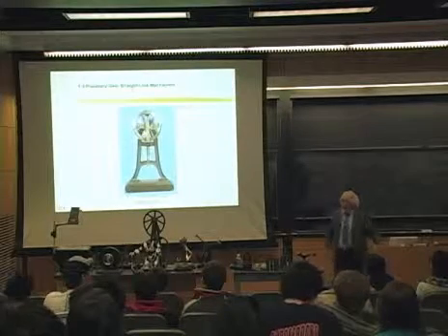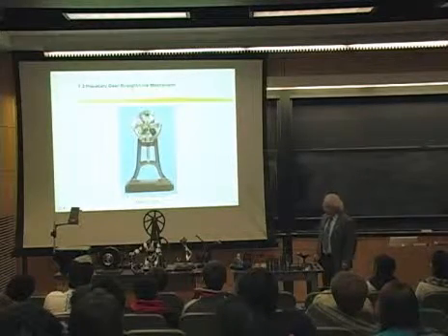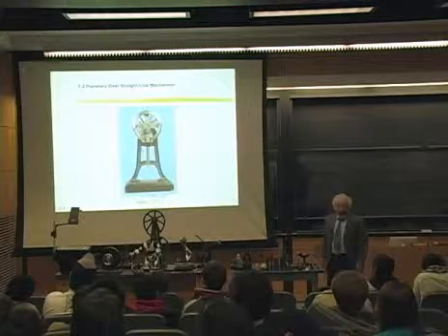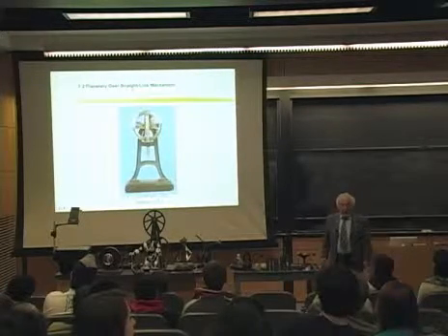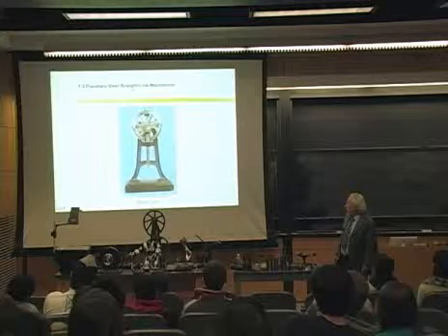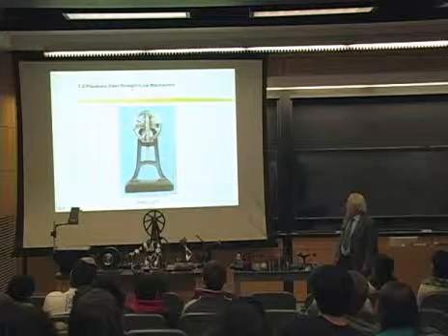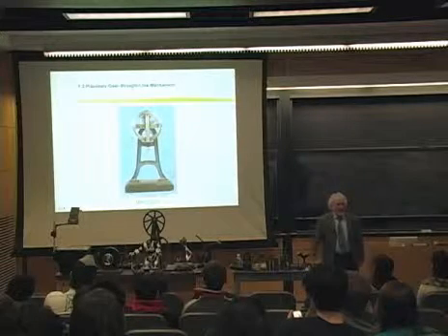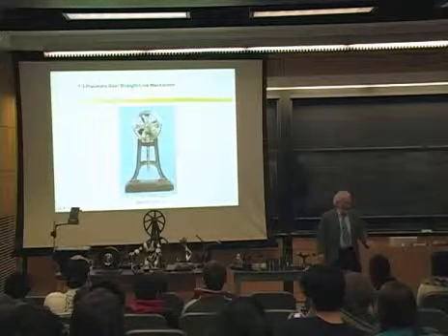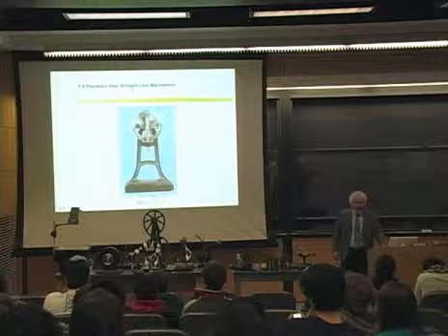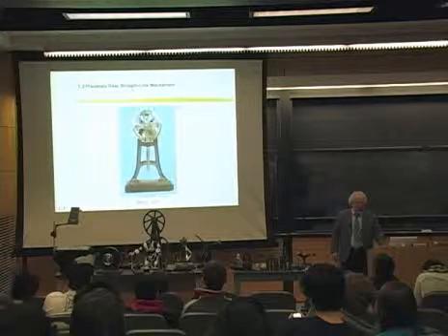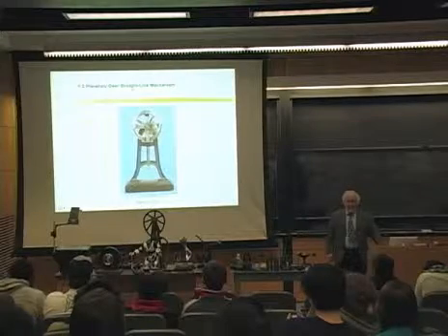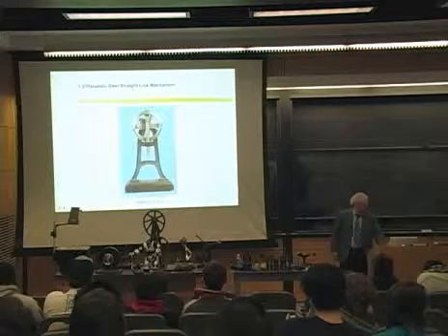And there are also gears here. So this is a planetary gear, a special planetary gear, in which the pinion is half the diameter of the large gear. And what that produces is that the motion on the outside of the pinion will produce an exact straight line motion. And in the next lecture we'll talk about how you can produce particular mathematical motions with mechanisms.